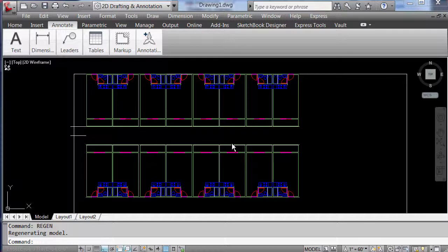Basically, in a nutshell, AutoCAD often tries to save memory by just quickly creating what's called a virtual draw. It just makes a really lightweight draw. By telling it to redraw, you're telling it to quickly refresh and get your ducks in a row, so to speak, but in a very quick fashion. Okay, as opposed to a regen where it goes down into the database and makes sure everything is aligned. It's just a subtle little difference.